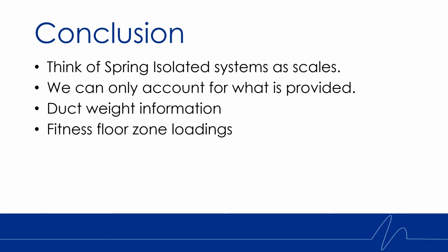Our project coordinators can only account for the weights of what has been provided. If you ever have a question of, does Kinetics need this? Please default to yes. We have no problem in sifting through additional information to ensure that your project is selected and designed accordingly. Most importantly, and a large hurdle that we face, is duct weight information. As mentioned before, duct weights can vary for the gauge of the metal, dual wall insulated, and other contributing factors. A duct plan is always appreciated, and if supported, the hang point locations and weights.